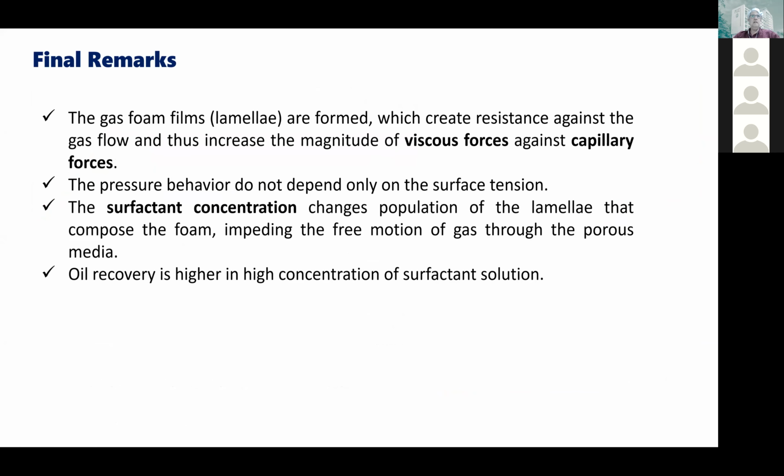Okay, so as a final remark here, we see that we are able to form these foams or lamellae when the gas is displacing the surfactant solution. That changes the pressure distribution inside the pore space, and that pressure distribution is able to displace the oil that was trapped by capillarity.